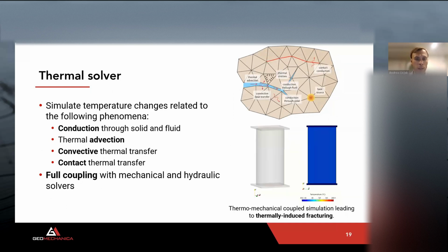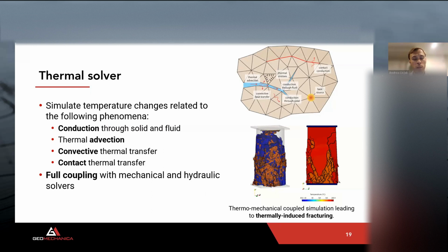The third solver, which was added more recently, especially in 3 dimensions, is the thermal solver. With the thermal solver, you can simulate temperature variation inside the rock mass due to several phenomena. First one is the conduction through the solid and the fluid. Then we have the thermal advection due to the bulk movement of the fluid inside the fractures. There's the convective thermal transfer, which is a transfer of energy between the two phases, the fluid and the solid rock. This is important, for example, for geothermal applications. And a contact thermal transfer model, which captures the thermal transfer across discontinuities.